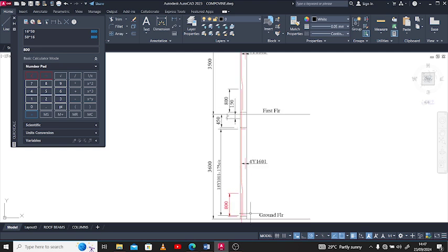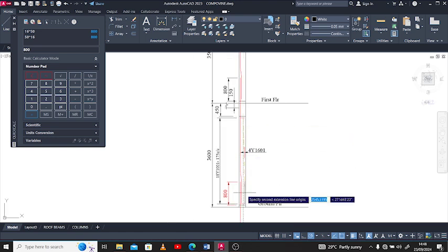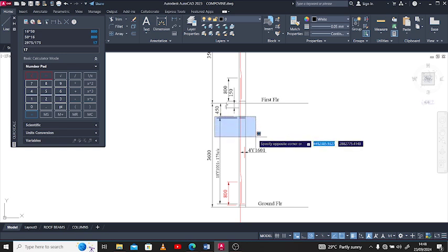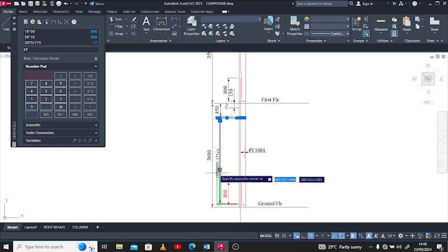So how do we know this is 18? The span of the stirrup, which is 2975 in my calculator, divided by 175, which is the recommended spacing from the design, gives 17, plus 1, that's 18. The same thing applies to the upper floor, apart from the fact that the length there is a little bit smaller.